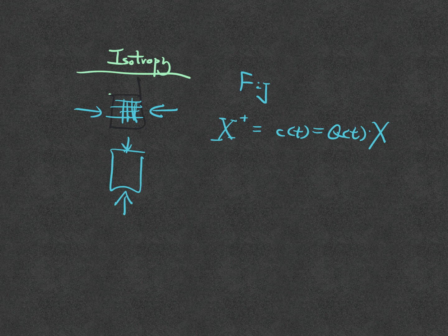as we showed before, if I define the deformation gradient this way, then the new configuration will give us F^+ equal to F·Q^T.